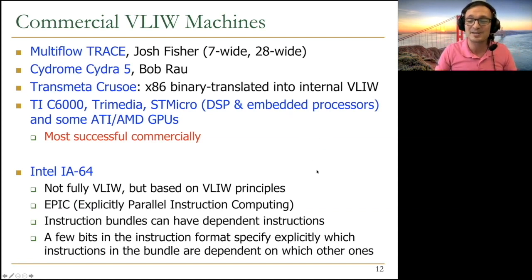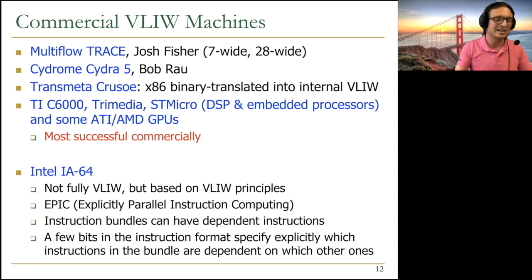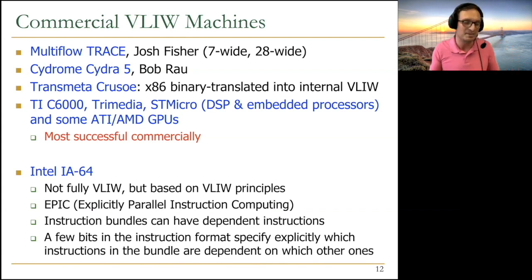And there's a question, how is error handling done if instructions are committed concurrently? Well, basically, you need to check the errors on a per instruction basis. And if you cannot commit the entire instruction, yes, you may need to break it at that point. So that's a very good point, actually. If the instructions are committed concurrently, it's fine if there are no exceptions. But if there are exceptions, you need to handle them in a manner. And VLIW architecture specifies exception handling also. So you need to look at the ISA manual in terms of how the exceptions and interrupts should be handled in a VLIW machine. So that's a very good question.